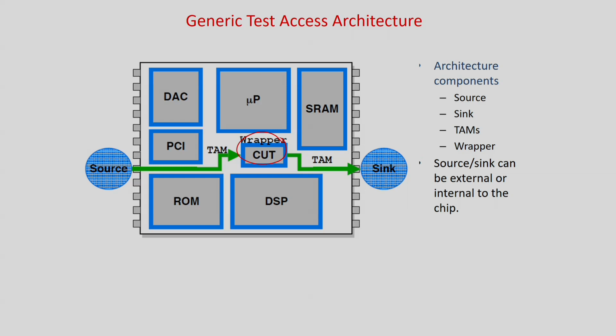As I have shown you, this boundary scan method can also be one way of having a TAM, one way of accessing the test lines. It can also be a very highly critical part of the core which has to be tested. Many test patterns have to be given and recorded, so I can put some dedicated input output lines for that. For all the others, I can put maybe a scan register, because testing by scan method will take a long time and more test time will be required. So if fewer patterns can do the testing, I can connect to a scan register.